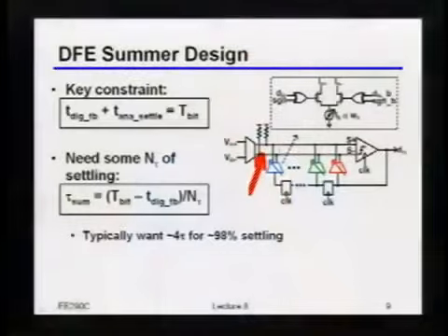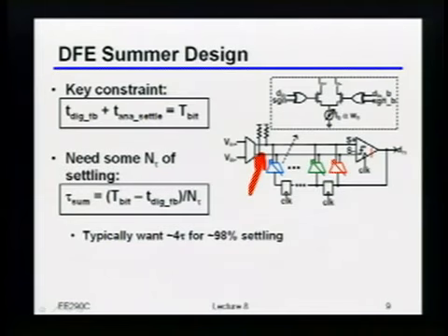Now, by the way, not only do I have to get that 8 or 9 gigahertz from just a standard amplifier, but remember, there's all these extra current steering switches sitting there, right? Each one of those things has some cap that it's going to be adding to your output. So that means it's going to be even harder to get that speed constraint, okay?